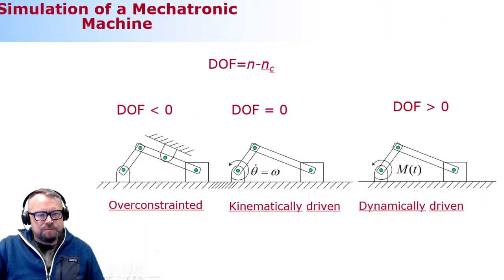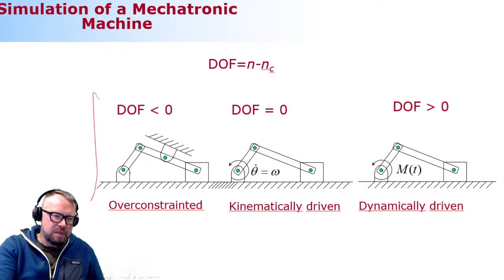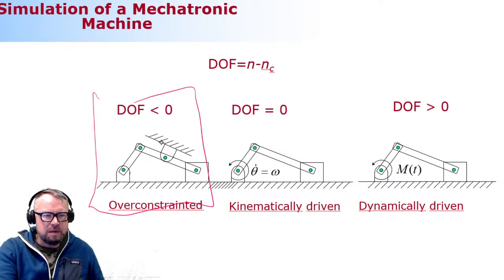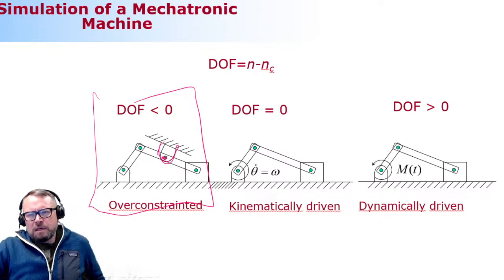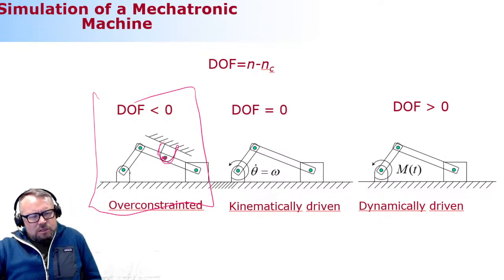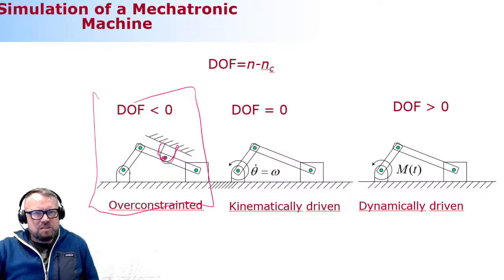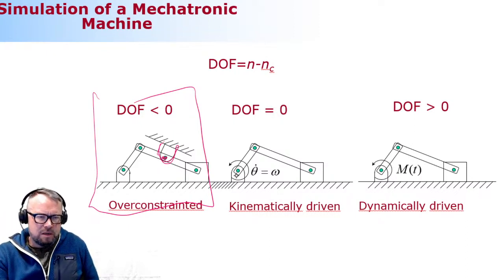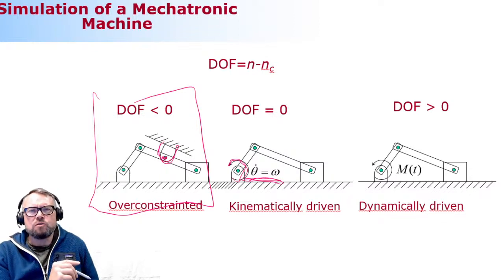Here are the different scenarios. So our constrained system is a system that cannot move because I'm introducing an additional revolute joint here in the connecting rod such that the connecting rod is attached to ground. So this system cannot move. So it's stuck. Then I can introduce a constraint. And the constraint could be the fact that this crankshaft has to follow the equation that is provided here. So this is a driven constraint. So it's no longer free to move as it wants, but it has to follow this.